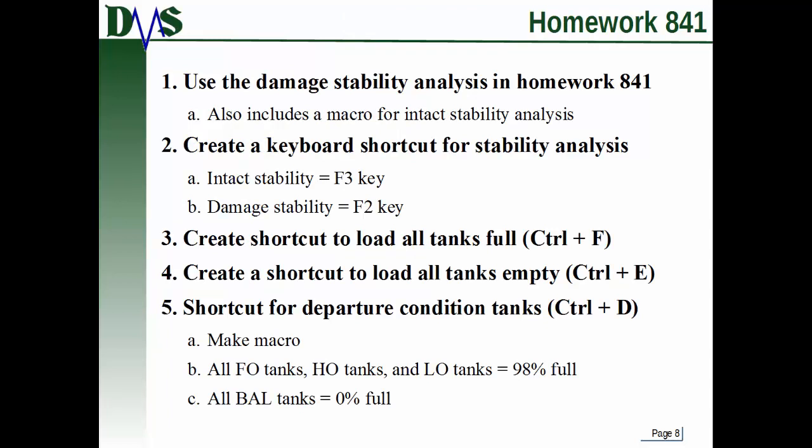Okay, so let's practice this. Homework number 841. What I'd like you to do is, there's a damage stability run file in homework number 841, and that also now includes a new macro for intact stability analysis. So what I would like you to do is create 2 keyboard shortcut keys for the stability analysis. I'd like the intact stability analysis to be assigned to the F3 key. So that macro for intact stability should be the F3 key. And then I'd like the damage stability analysis to be assigned to the F2 key.